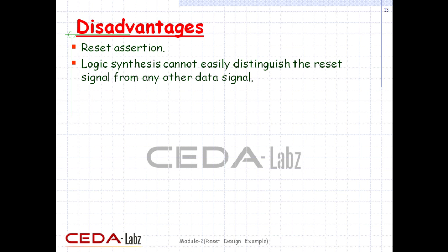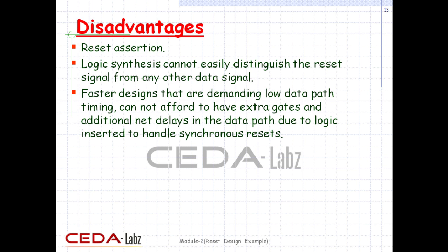In some power-saving designs, the clock is gated. In such designs, only a synchronous reset will work. Faster designs that are demanding low data path timing cannot afford to have extra gates and additional net delays in the data path due to logic inserted to handle synchronous resets.